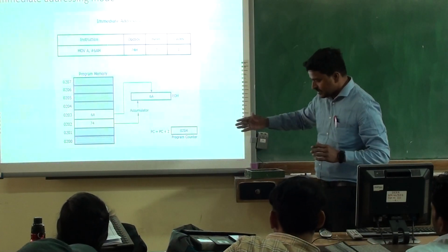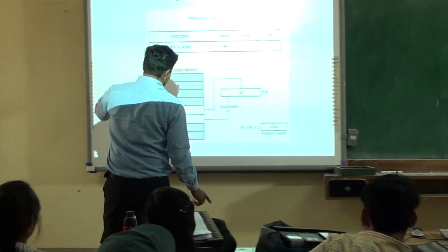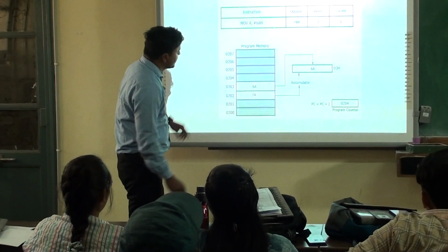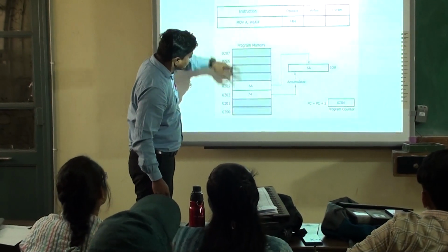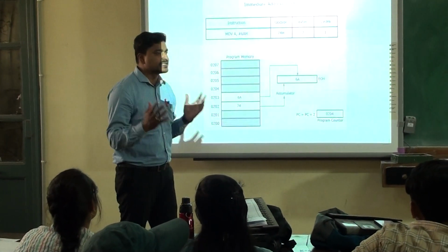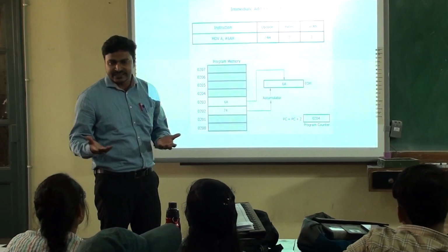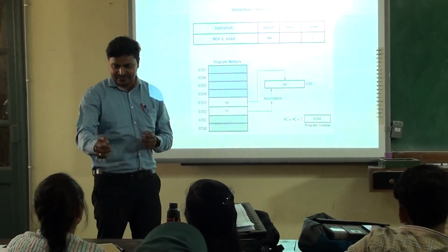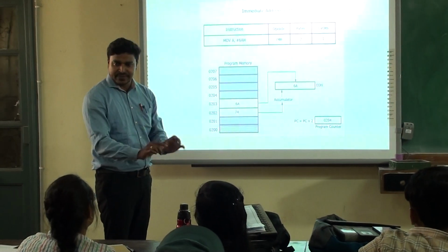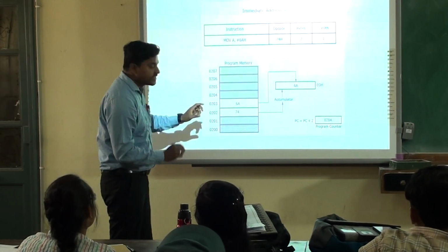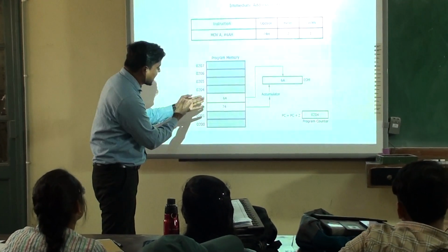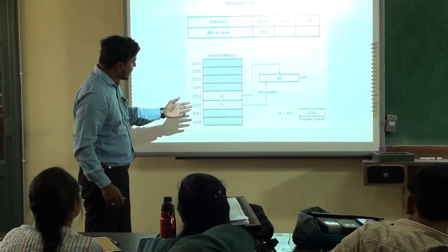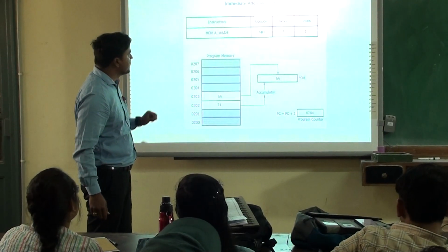When we start here, this is your program memory. This 74 is the numeric code. MOV A is 74 because the machine doesn't understand words like A, B, C, D. Your mobile or keyboard typing it doesn't understand. It understands only numbers, like hexadecimal 74. And this 6A is your immediate data.